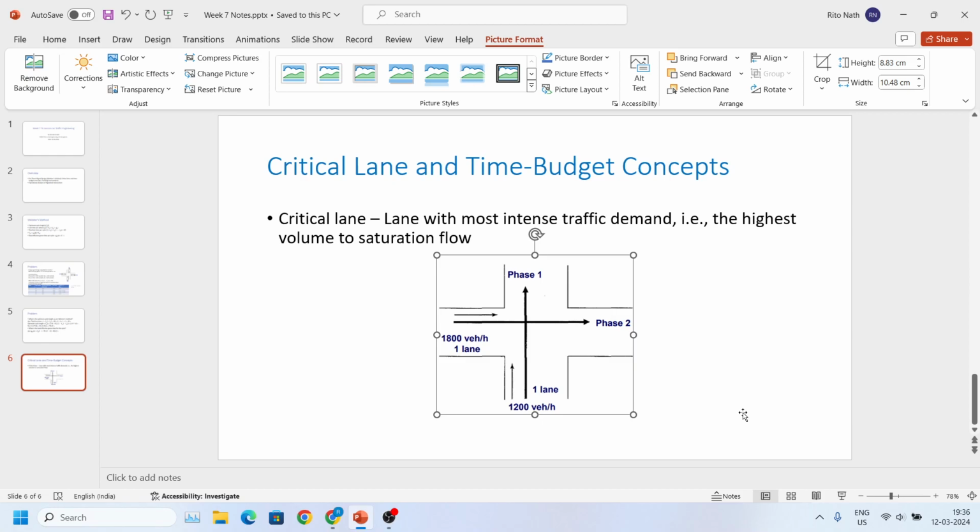You first can come up with the critical lane flows, and after that you can add those volumes that are given. The critical volume should be higher than what you need to accommodate, otherwise you might be falling short. In that case you have to check what could be the optimum cycle length.